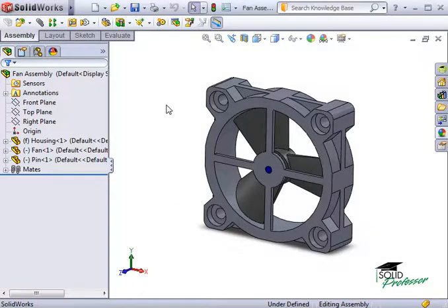Now, this is a good way to hide elements of your design that you want to keep secret, but this can be very useful when working on large assemblies with a group of other designers. For example, when designing a car, you can create a defeatured part for the engine while maintaining the references to the mounting bracket, which you can easily send to the chassis design team. Defeatured parts are very lightweight, and since there's no feature definition, your defeatured assembly will be safe from inadvertent changes from other design teams.